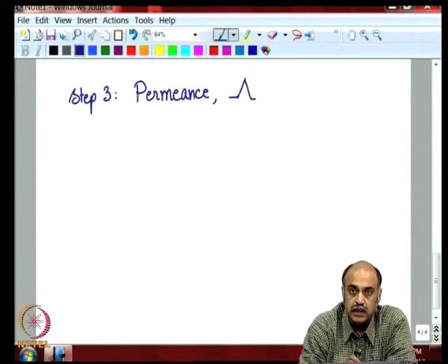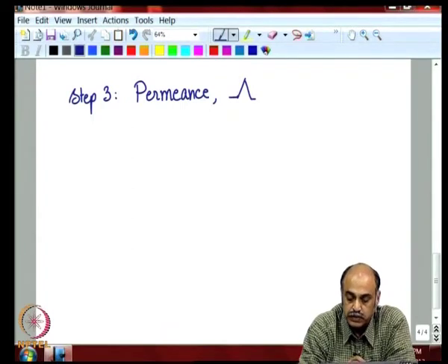However, in the case of the inductance, there is need for energy storage, and therefore, the reluctance has to be higher, and if the reluctance is higher, the permeance will be lower.